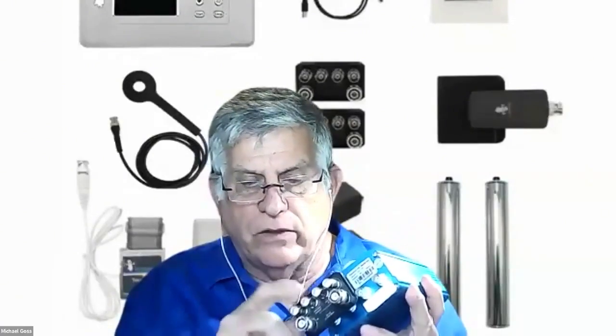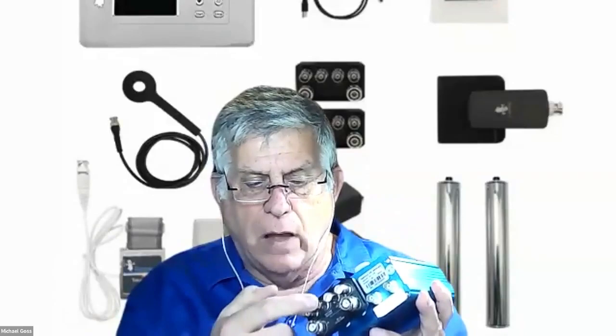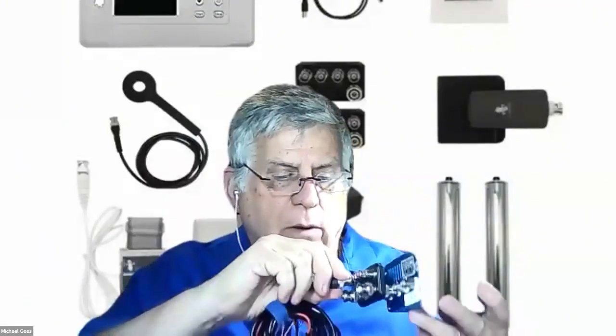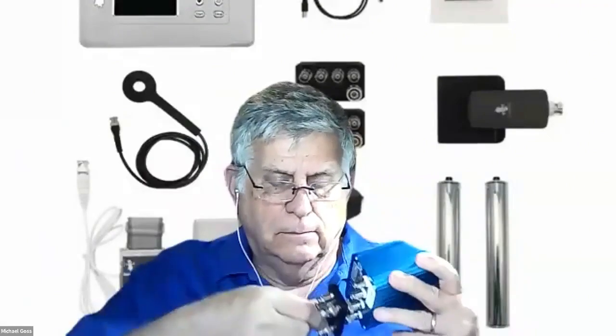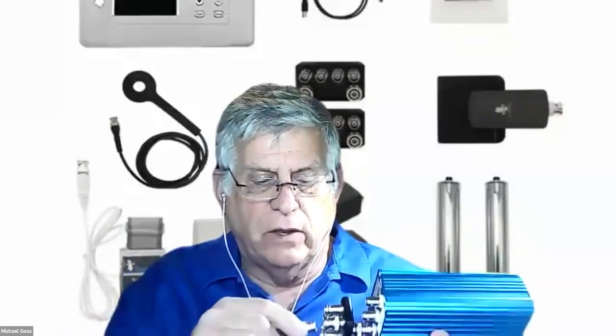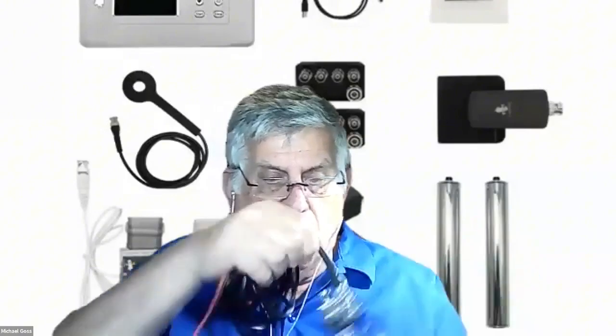Okay. Then generally you're going to use the high power port. That's this one here. That's the second one in, on the top, second one in from the left. So now we have my cable. So we're going to hook that up to the high power port, just like that. If you've never used BNC connectors, and I've had people ask about that one, this is a BNC connector. BNC connectors, there's these little pins on here. They go on the pin, and then you turn them a quarter turn to lock them in place, and you can tell that it's locked in because it can't come off.